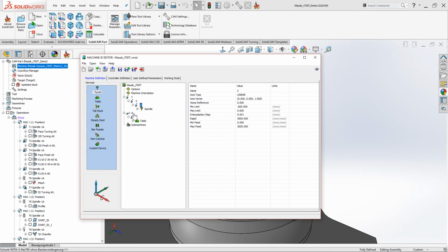Let me now go to the A-axis, following the rules that I explained a few moments ago with the linear axes, negative and positive. You can know that those two axes are rotary axes, and since they are on the table, this vector will be negative.